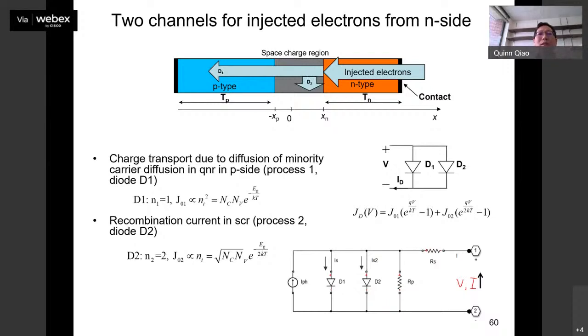So the same thing for you. If you see the two slopes under the illumination, but you don't see the two slopes in the dark, that may tell you that you have a huge defect or something there that can slow down the charge transport in that range of the voltage. That doesn't mean your entire device has two diodes, but since that defect caused the issue, it looks like a two diode system. Yes, in the dark IV characteristic we are not seeing this type of behavior, but it is generally available in the light IV characteristic.